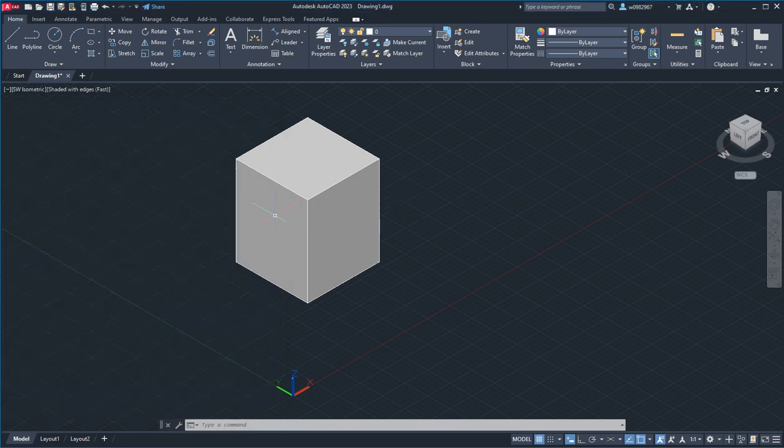To locate the center, we're going to use a line. We can use a line or a polyline. You can use your line as long as you highlight a face and then start drawing when the face is highlighted. We're going to start at the middle of this face. So midpoint, MID, point to the middle and then go down, and make sure your ortho is on, and then go down 20, and that will be the center of the circle.